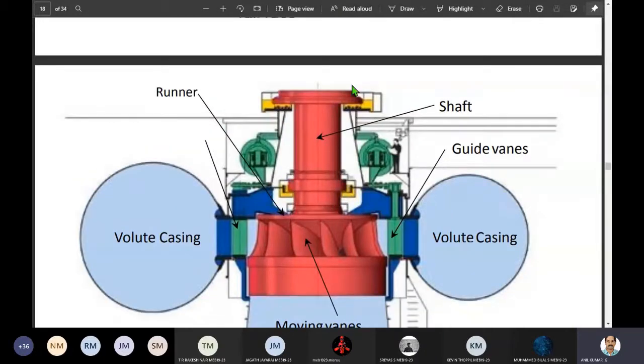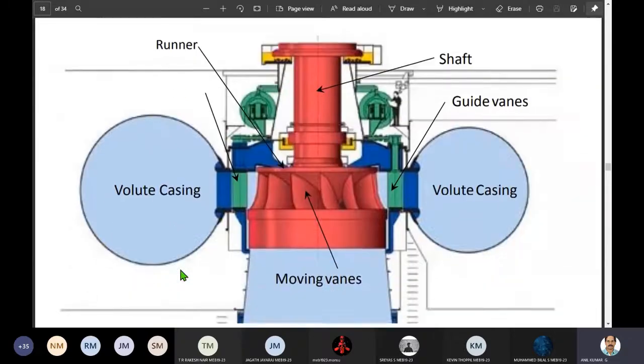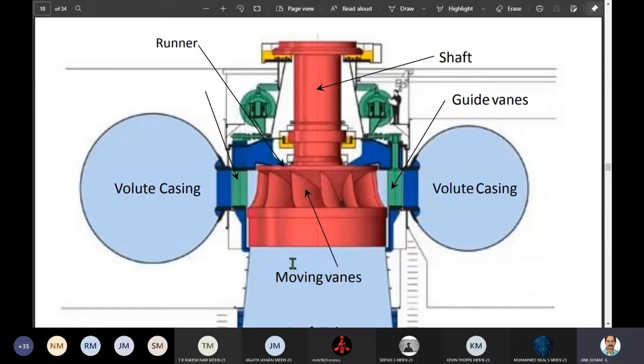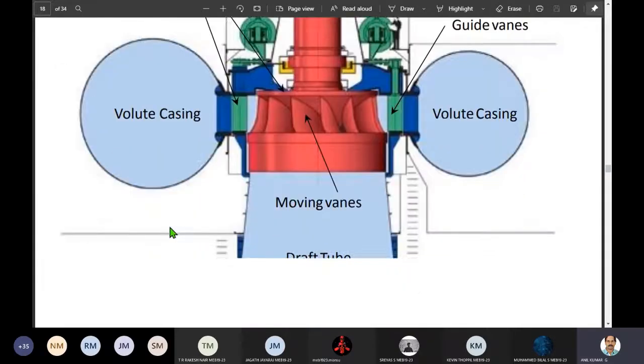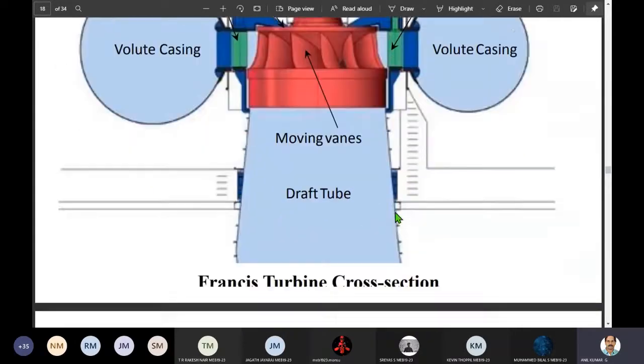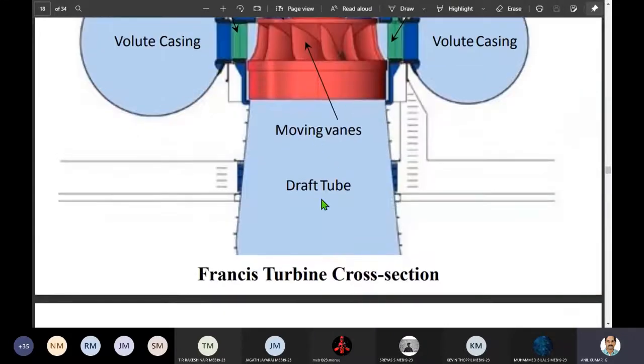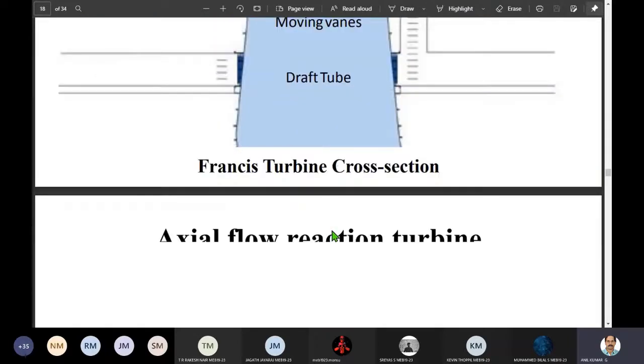And you have the turbine runner, generator above that. This is the turbine runner, and the scroll casing, the casing, is in cut section view. So just like the two circles shown over here are part of that cut section if you take the casing. Just like if you cut a tire of an automobile, the toroidal shape will give two circles. Here one will be small and the other will be big in this case because it is made in that way. Progressively, as the flow occurs, the area of flow has to be reduced to convert the pressure energy into kinetic energy in a reaction turbine. And the conduit or the pipe through which water is discharged in a reaction turbine is called the draft tube.